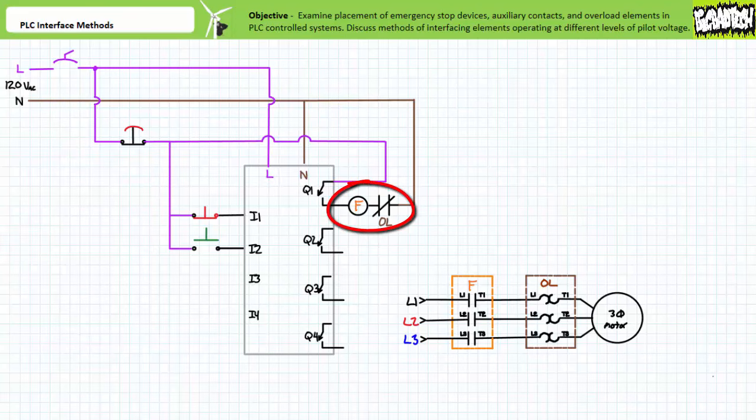This hardwired connection between the F contactor coil and the normally closed set of overload contacts may seem to be an injudicious use of a PLC with a stated ability of flexibility without the time-consuming necessity of rewiring. However, this is a common practice for reasons of safety. Similar to our earlier discussion about well-placed e-stops, note the physical connection between the F contactor coil and the normally closed set of overload contacts allows the overload to have the last say as to whether the F contactor closes or not, and never surrenders complete authority to the PLC.